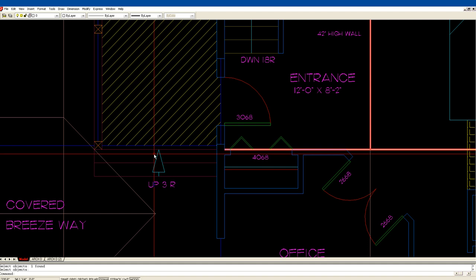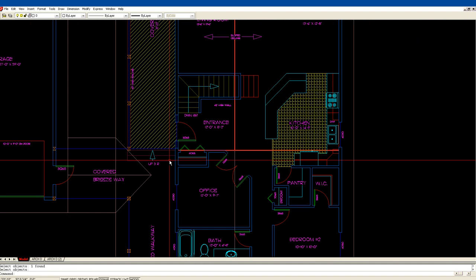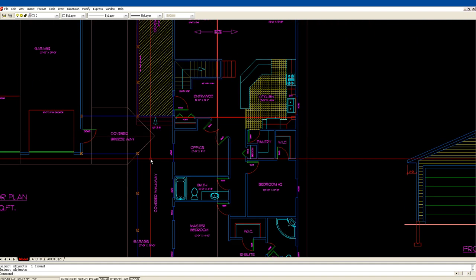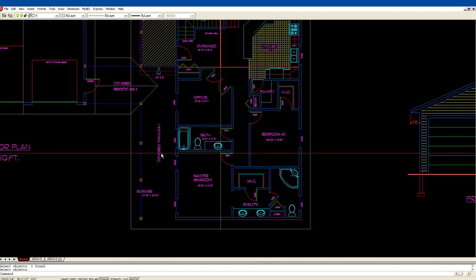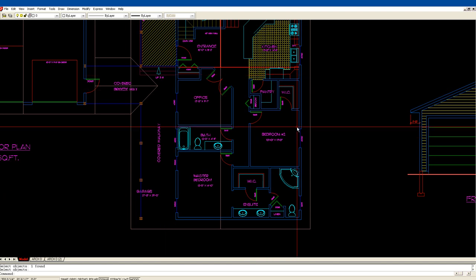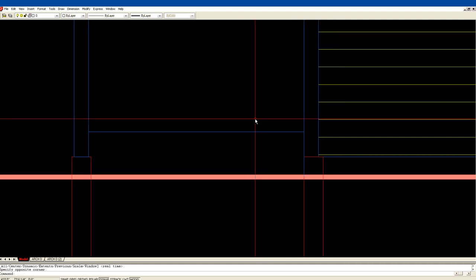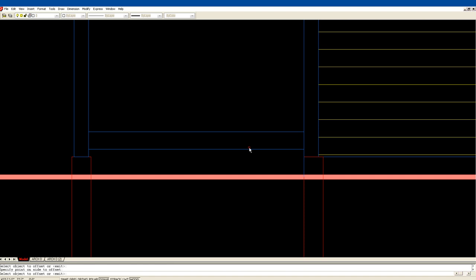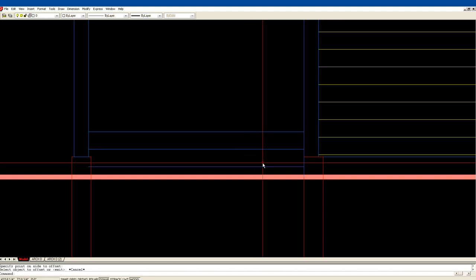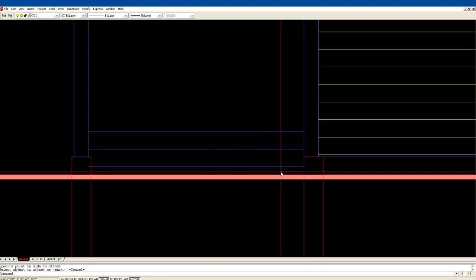Now this all depends on how he grades. He may keep his grade lower and then he'd need another stair. And he's probably going to put in some concrete here for a sidewalk, a sidewalk walking all alongside of this building, and then he has to go up some stairs. Well, we try to keep stairs to 7 inches like we did inside of the house. So offset 7. There would be my first step, there would be my second step, and then this would be the level of his sidewalk. He would build up more concrete to that level.